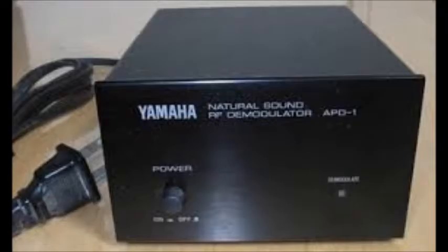The advantage of this process is that very selective fixed frequency filters can be used, and these far outperform any variable frequency ones. Now these selected and desired frequencies are fed into the demodulator, and the demodulator recovers the information contained in the modulated carrier wave. Here the desired frequency is separated from the carrier wave, and hence we get the required frequency with minimized signal loss, and this required frequency is the one that we were trying to tune into.